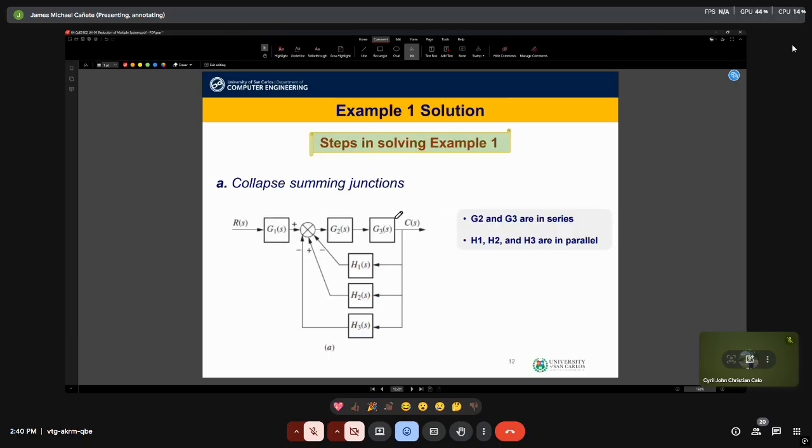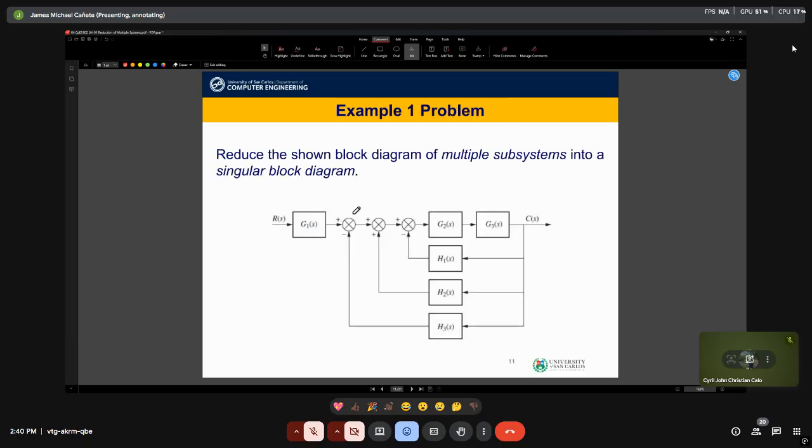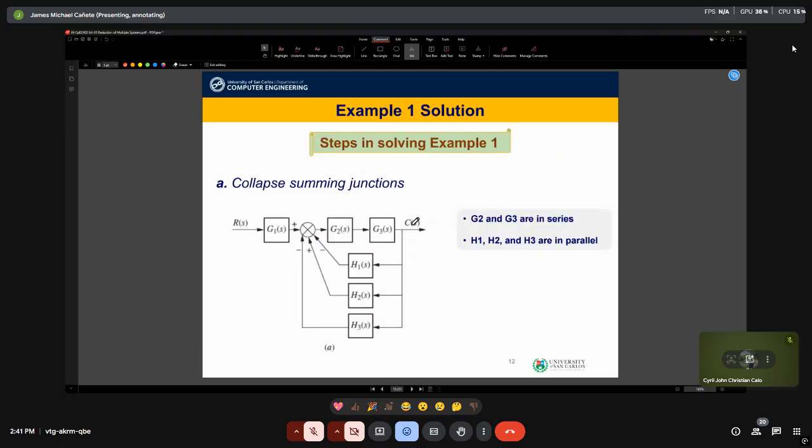In this example, of course, mathematically, if we want to combine these two, we just need to add, or this arrow here is simply this plus this. Or you can take all of these two arrows and add them to one summing junction. And in fact, you can do this again in this third summing junction. So the simplification that we can do is combine the summing junctions,